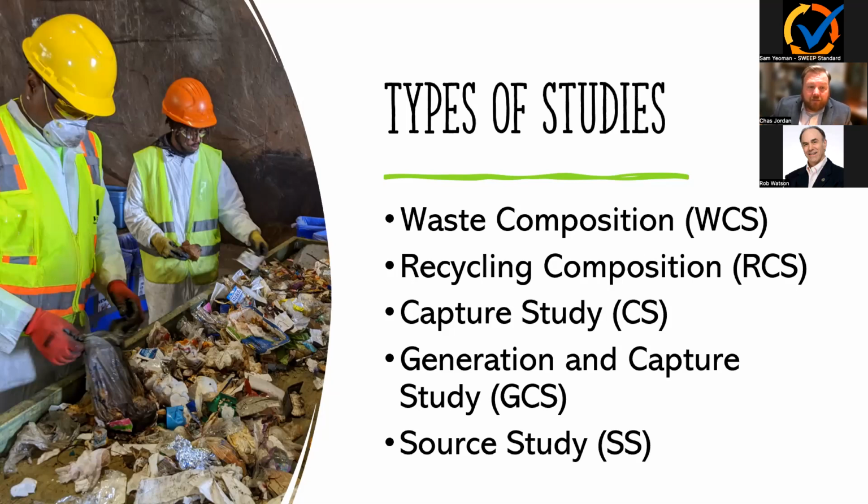And you can see that here by the workers in this photo. These materials are separated and then weighed out versus the total weight of the sample to determine a percentage. And through the sorting of many samples, depends on the size of the organization, but we usually aim for 30 to 50, a study becomes statistically accurate to the entirety of the waste stream.